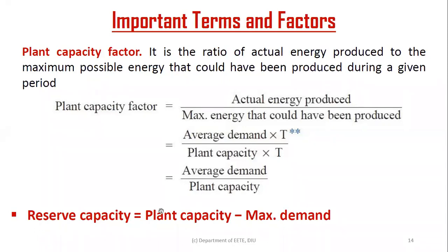The next thing is reserve capacity. I already discussed what reserve capacity is. The reserve capacity equals the plant capacity minus the maximum demand. Okay, the maximum demand, plant capacity minus the maximum.